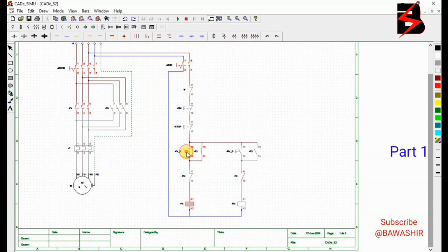So when we switch on forward, you will see that the motor is running in clockwise direction. And since this contact is for this one, it is self-holding, then here this contact is for this coil here. It has opened. So when it opens, however much you switch on this other direction, it can't turn on because this contact here is open. That is what we call interlock. What you have to do is first to stop. So when you stop, it goes off and it closes again.